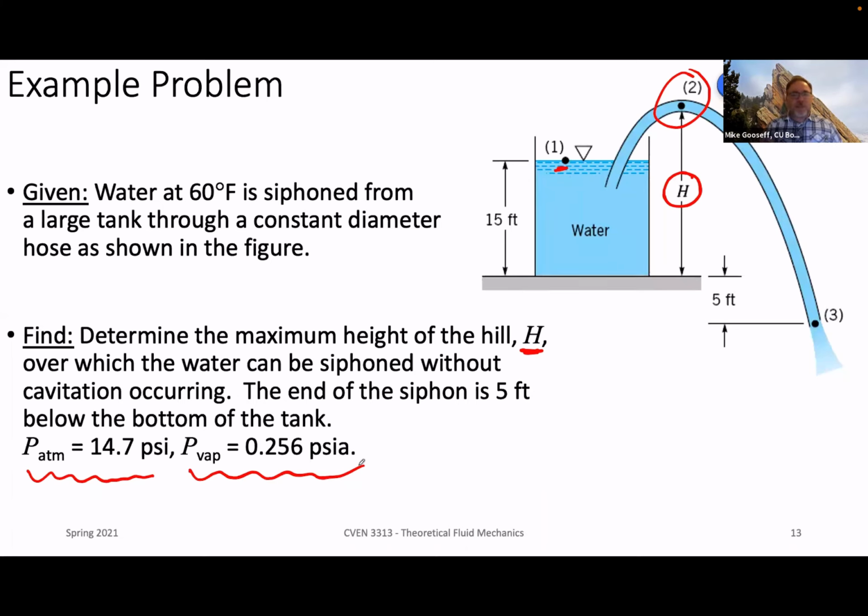One thing real quick. I don't encourage you to ever do this, but one reason that we can siphon or have water move from the tank on the left to the outlet on the right is that look at what happens to our total energy. We reduce it so much by going 5 feet below the bottom of our reservoir that basically we set up a gradient so that water wants to move out in that direction. This is not unlike people trying to siphon gasoline from cars.